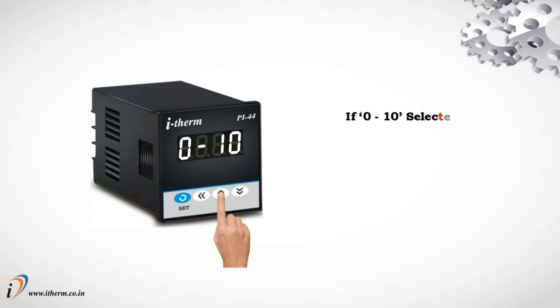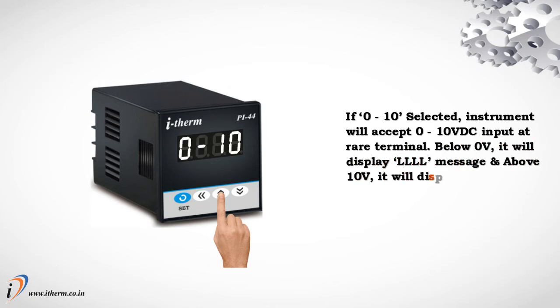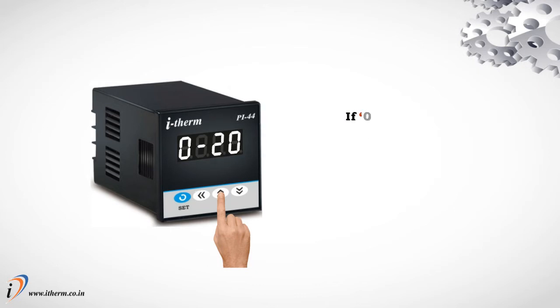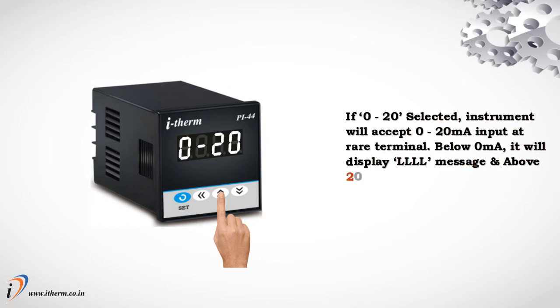If 0 to 10 selected, instrument will accept 0 to 10 volt DC input at rear terminal. Below 0 volt, it will display L message, and above 10 volt, it will display H message. If 0 to 20 selected, instrument will accept 0 to 20 mA input at rear terminal. Below 0 mA, it will display L message, and above 20 mA, it will display H message.